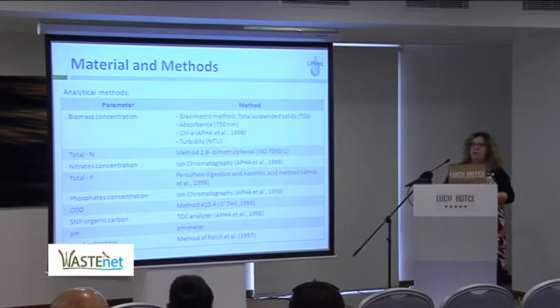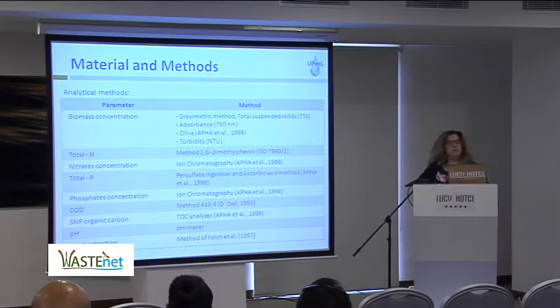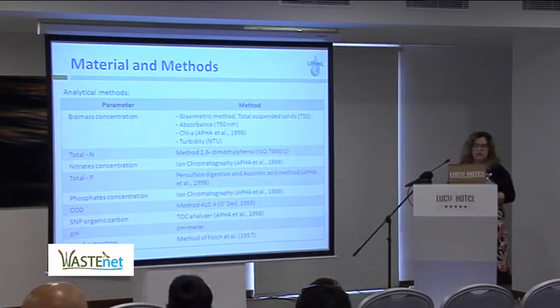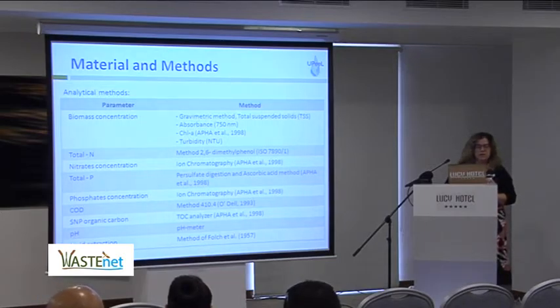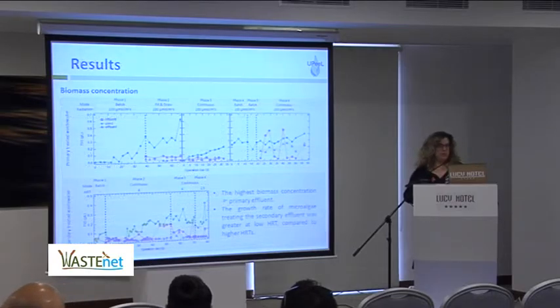In this table, we see the measurements which we conducted in our experiments. We measured biomass concentration with a gravimetric method, absorbance, chlorophyll a, and turbidity. We also measured total nitrogen, nitrate concentration, total phosphorus, phosphate concentration, chemical oxygen demand, soluble organic carbon, pH, and finally the lipid extraction, which was made from the dry biomass of microalgae.